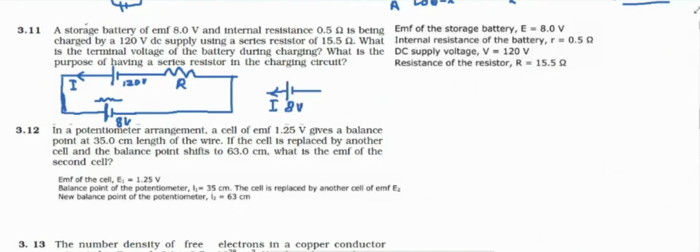So like this, current will come out from the positive terminal for the 8 volt battery at the time of discharge. Now this is a case of charging, so current should flow in the opposite direction like this, because we want to reverse all the reactions inside the cell. Whatever chemical reactions you obtained when the cell discharges, now you need to get opposite reactions during charging. So current also should enter in the opposite direction. That is the reason the positive of the charging battery we need to connect with the positive of the secondary cell.